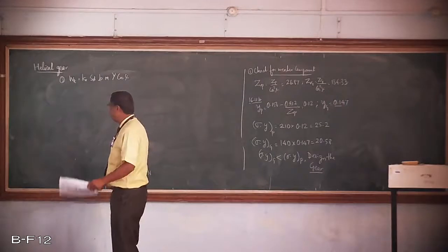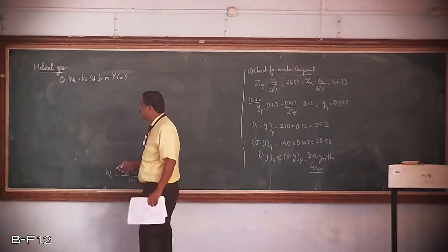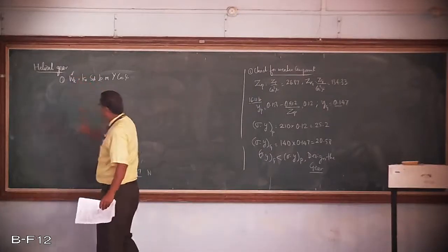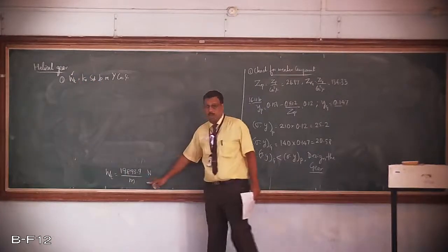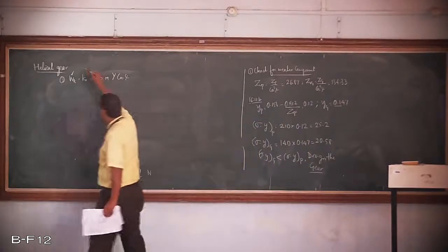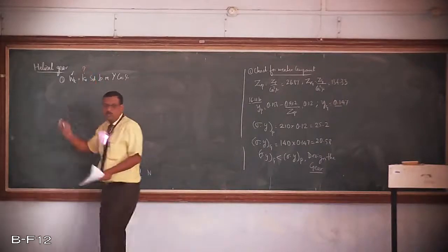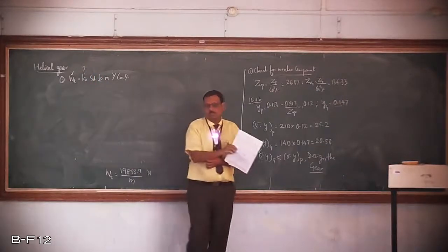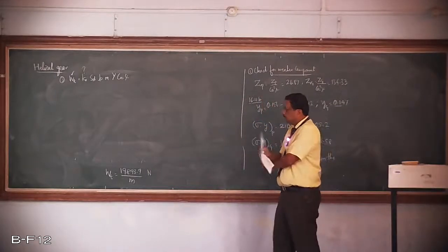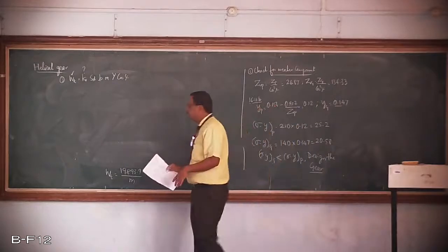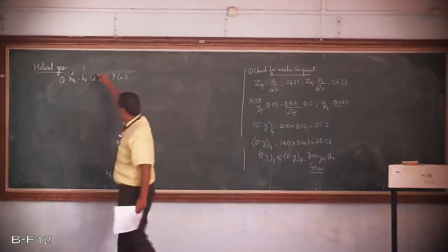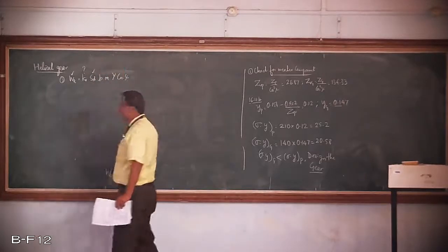Now, we will see what values we know in this equation. WT we have calculated, therefore we know the value of WT in terms of the module. kV, the velocity factor: either you can assume some value like 0.5, 0.6 or whatever, or else you can keep it as kV itself, the way we have solved in the previous class. SD, yes, we know the value of the static strength for the gear.